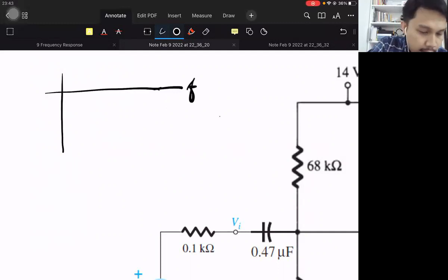Frequency and gain in dB, no? So in our mid-range, for which our signal is unaffected, the factor is multiplied by 1 only, right? So a factor of 1, I convert it into dB, 20 log of 1, I mean. So 20 log 1 is 0, okay?